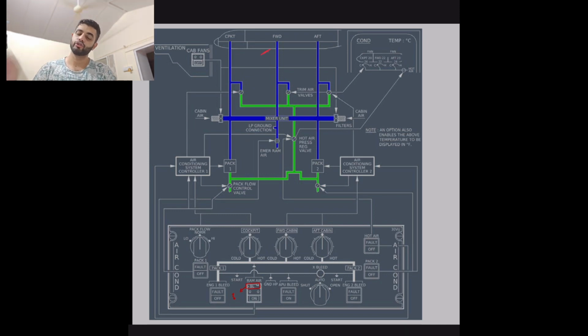During landing, once you have landed, main landing gears are compressed and speed is above 70 knots, it remains closed. It will open 20 seconds after speeds go below 70 knots.